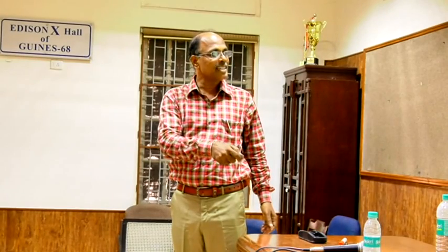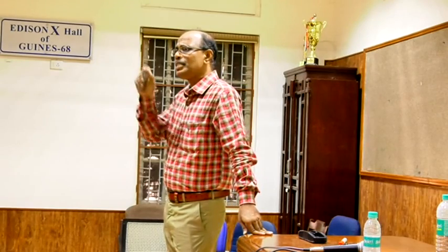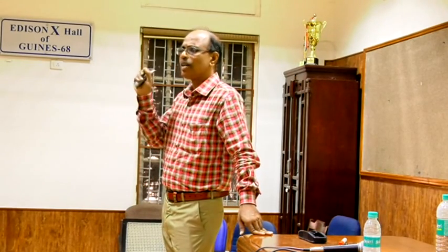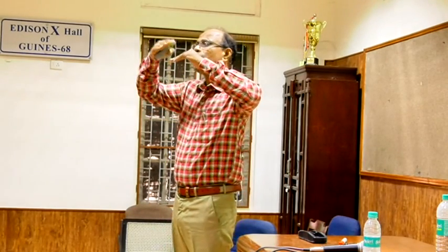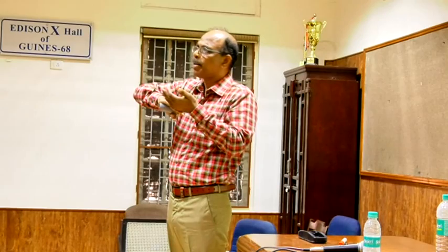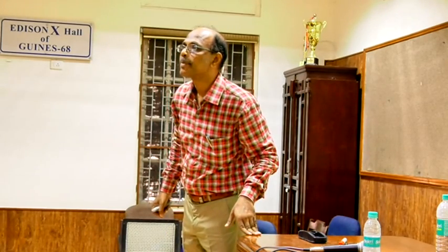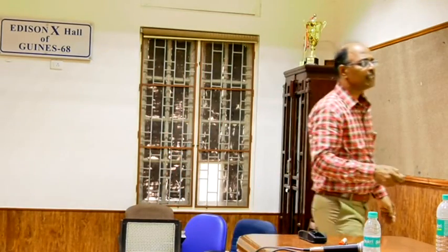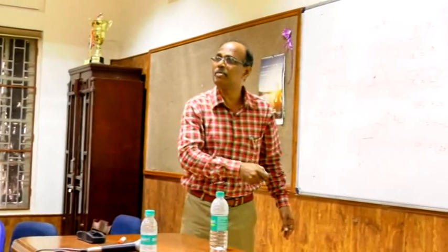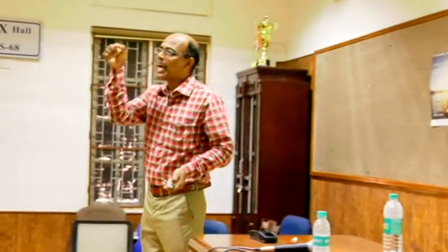And again, this is called the Jacobian matrix. This is the correction vector, mismatch vector. And in general, once you form the Jacobian matrix, and if you observe the equations, if you compare the upper half and lower half, only one variable is missing. Because of that, the lower half element will be different from the upper half element. So only one variable is missing. If you add that variable, both will be equal.